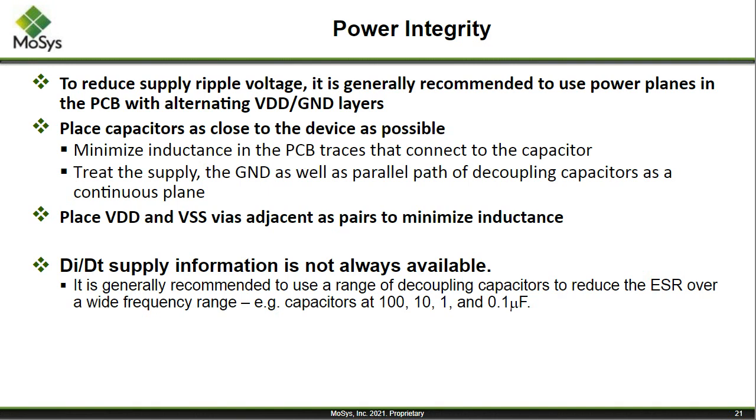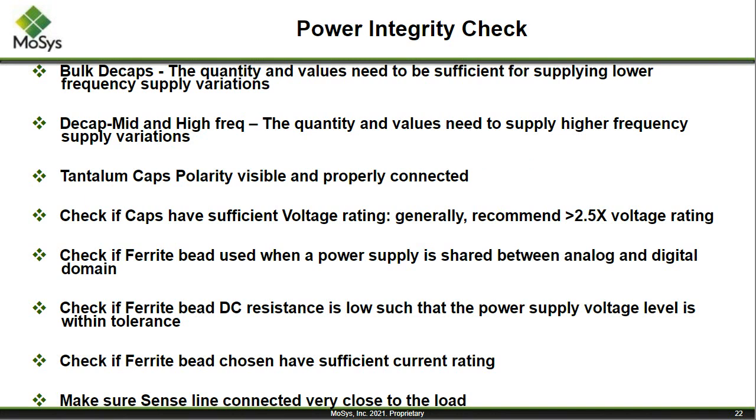So the safest thing to do is use a range of capacitors, right? You want to use different decoupling capacitors. You want some bulk decoupling, and then you want some high frequency decoupling as well. So that's where you'll end up with a series of these, 100 mic to 0.01 mics, to some bulk decoupling caps. So again, I'll be really quick here. I know I'm using a lot of time.